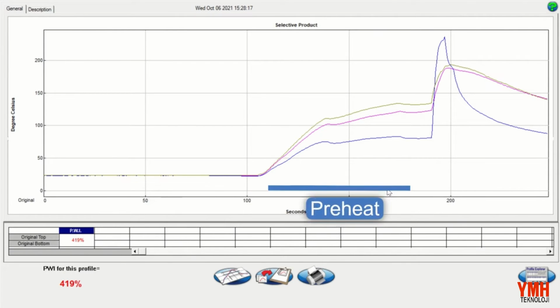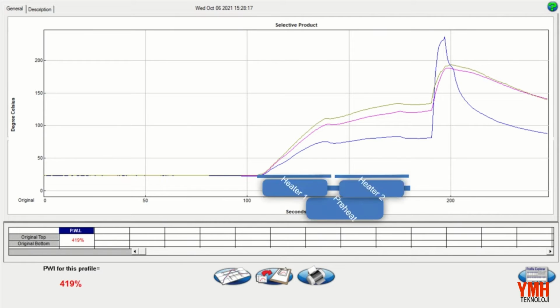Next, let's focus on the preheat area. It is possible to analyze the data and recognize the number of preheat zones that your selective solder machine has. This can be clearly visible in some selective solder machines and harder to differentiate in others. A good evaluation of your selective soldering process is important to have a good perception of the different preheater influence on the profile data. Note, if you cannot clearly differentiate the various preheat zones using the product thermocouples on the PCB, you could use an AirTC with no process specifications applied to clearly show the various zone separations.